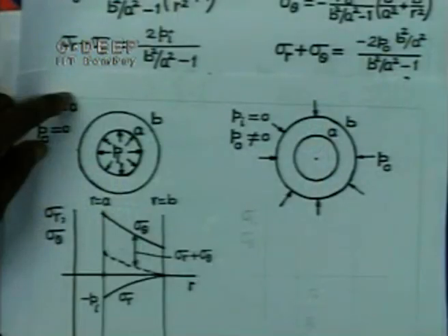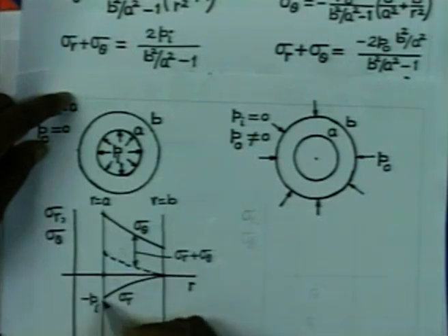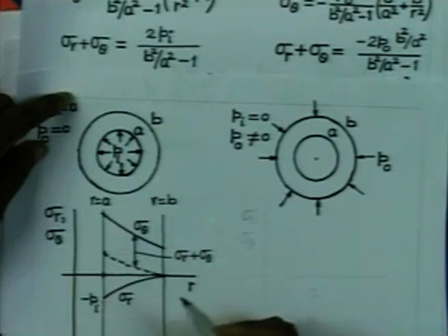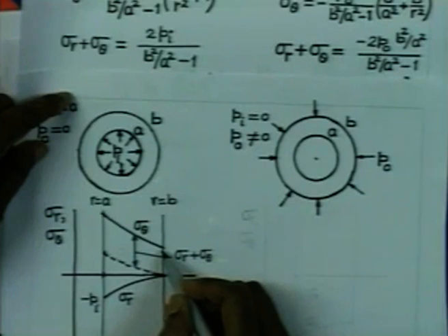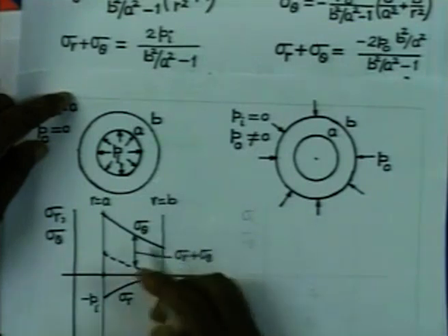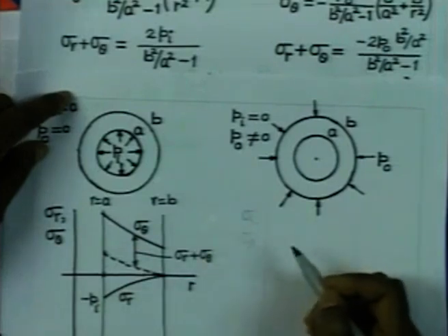So, you see that the maximum stress in the thick cylinder is going to be the hoop stress at the internal radius, and the maximum stress in the radial direction is at the outer radius. At the outer radius we have hoop stress which is going to be tensile, and it has a magnitude less compared to the value at the internal radius.